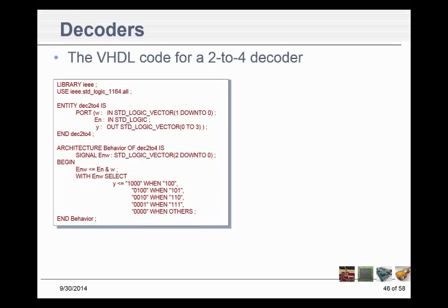And since we always see the most significant bit as the leftmost bit, it is probably a good rule of thumb for us to always use downto. Okay? In this case, I didn't. And look at the kind of mess it could get you in.